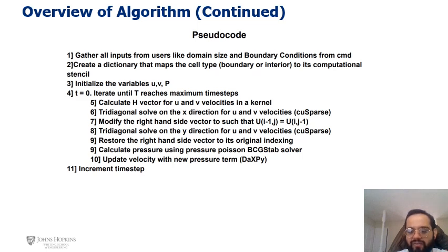Now converting from row based indexing to column based indexing is a time consuming step, and doing that in each time step can be a big time sink. But fortunately, since each particular grid point is independent, and its mapping in a column based indexing is also independent, we can fully parallelize this step.